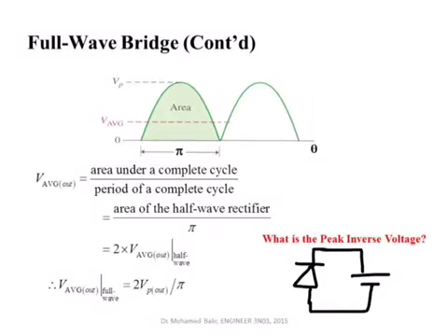Usually the breakdown voltage for these diodes is way higher than the values used in this circuit. So if the secondary voltage is 15 volts, we use diodes whose breakdown voltage is, say, equal to 30 volts. So we don't even have to worry about the breakdown voltage.